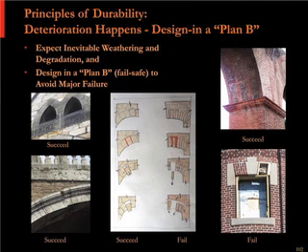But Norcross Brothers, who built basically all of Richardson's buildings, they shimmed every stone. So they had the same kind of idea going on with stone shims or chinking as you see in the Tuscan construction. So even though all the mortar was eroded, none of those stones had fallen, and that tower is 120 feet above the entrance to the building. So it avoided a catastrophic failure.